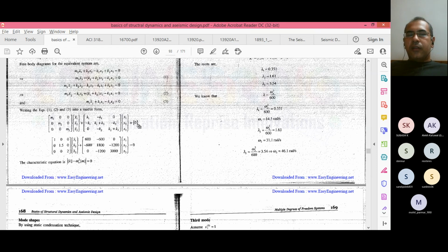We are not right now concerned about how much force is acting on the system. We are concerned about what is the building we have defined and created, and what is the basic, inherent behavior of the buildings. That's why external force is 0. Whatever the fundamental internal resistance is generated, that we want to calculate. That's why it is equal to 0. So for behavioral analysis, we keep it as 0. So this is part of behavioral assessment of the building.